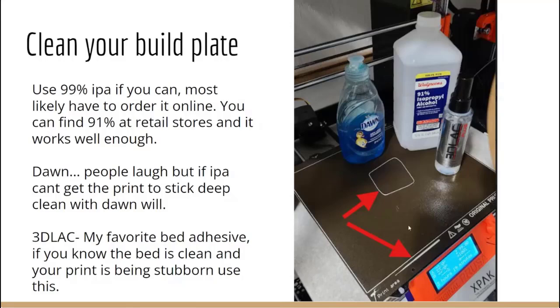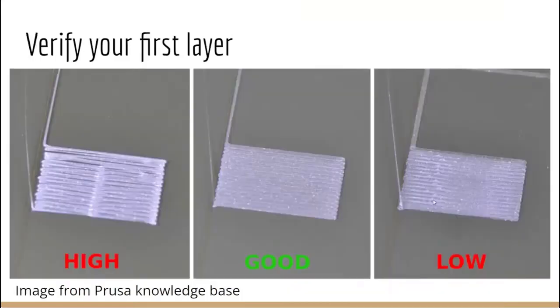So make sure your build plate's clean. Make sure it's free of the previous prints. Now you can go to your printer or go to your network and select print and tell it it's all systems go. Now, once the printer has started, this is kind of the last thing on your pre-flight checklist: you need to make sure that you have a good first layer. And you'll get an eye for this. Once it's dialed in, there are offsets on your printers that you'll use to get this layer perfect. But once it's set, don't touch anything. Don't manhandle your printer and make anything shift around or move, and you won't have to set this again.